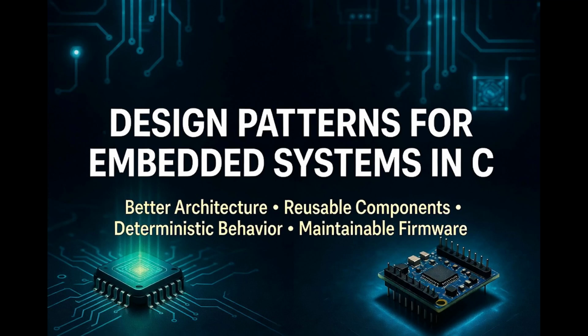Design patterns provide reusable engineering structures that help us build maintainable firmware, portable drivers, modular architectures, deterministic systems, and scalable embedded platforms. Even though C is not an object-oriented language, embedded engineers have evolved highly sophisticated architectural techniques using structures, function pointers, callbacks, opaque handles, state machines, queues, and static memory models.